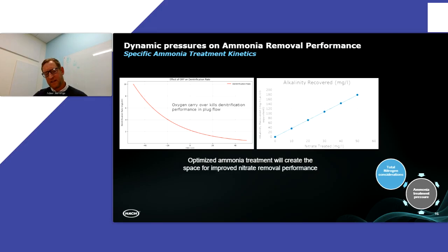And we take that nitrate-rich liquor, because when we're converting ammonia to nitrite and nitrate in an aerated system, your ammonia is going down, your nitrate is going up, and you can take that nitrate-rich liquor back around to a denitrification zone, a zone that doesn't have any air, an oxygen-free environment, and you have some carbon present.